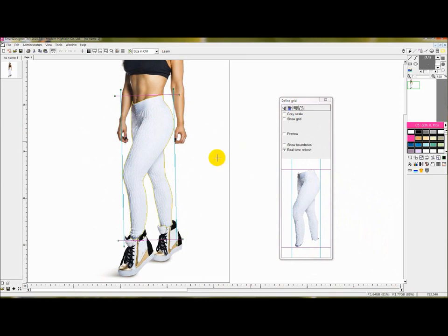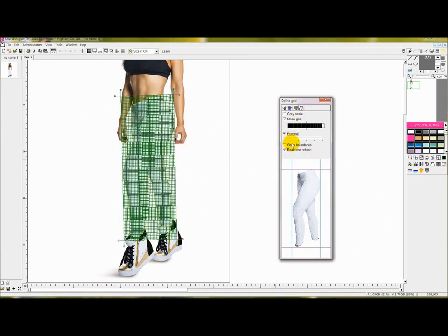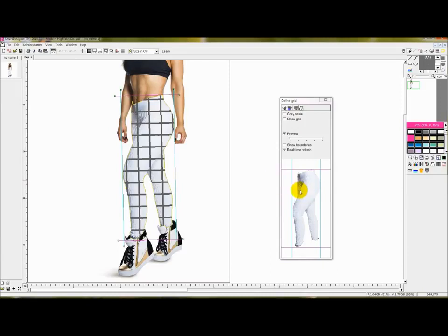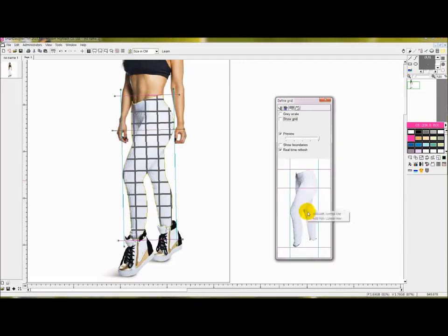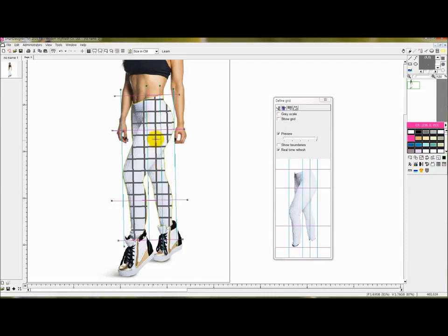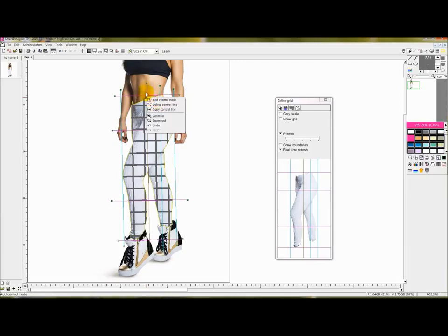And then on here, you can give the 3D effect. So click here. And you can add lines, the vertical line and horizontal line here. And I'm going to add the lines like this. And then you can change the line by giving the nodes. So click the right mouse button on the line and then click add control nodes.